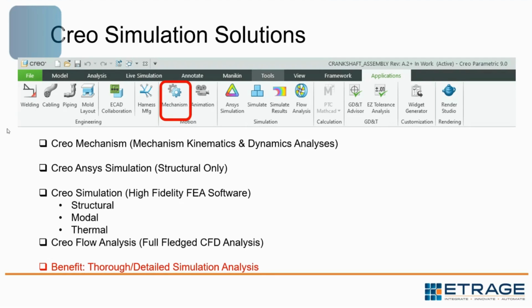And then the dynamic analyses within that, Creo Mechanism is where you can add into that any forces, I'll say, in the simulation. So by forces, what I mean is that's where you can add in any mass or additional point masses, or just the raw weight of the components themselves, again, via gravity and also the material density of the components you're simulating. You can also then add in there friction at any of the rotational or at any of the joint locations, right?